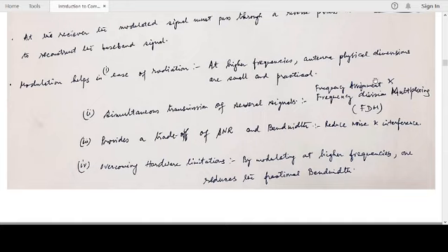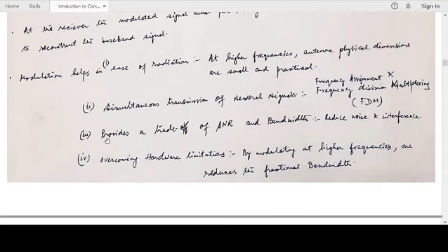So this is known as frequency assignment. Along with this comes something known as frequency division multiplexing. So what we can do in frequency division multiplexing is we can simultaneously transmit our information, or information from various sources, using the same carrier frequency, and henceforth this is an efficient transmission scheme by modulating. So it provides a trade-off of SNR and bandwidth.